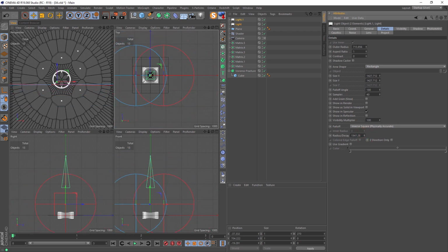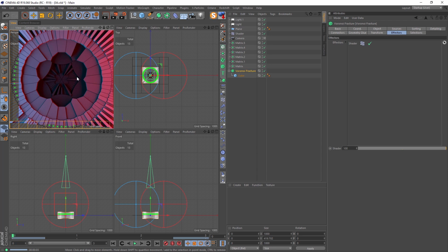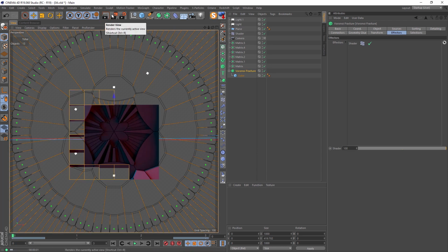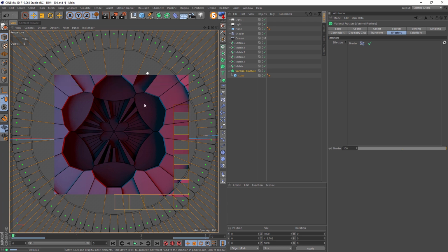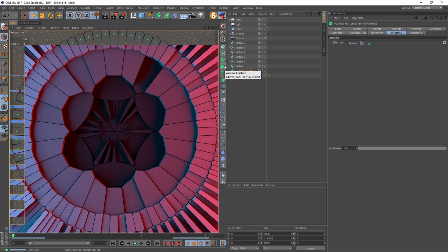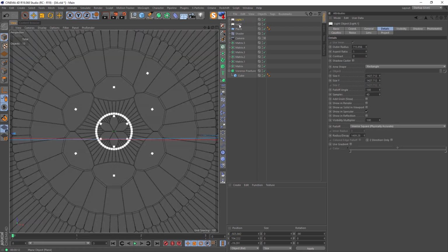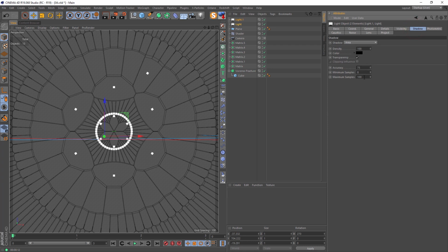Lower the radius because it will burn very strongly. And now you'll see that we have a very beautiful image with different colors, and almost no black. I don't want to dive into the settings, but to improve our lights, we go into shadow, and sometimes we need to up the maximum samples. So, for example, 256. It's up to you, you have to check this. So you have to know that we have maximum samples.